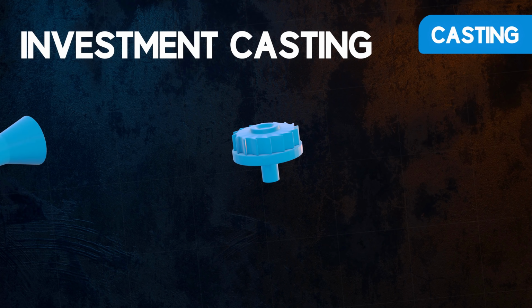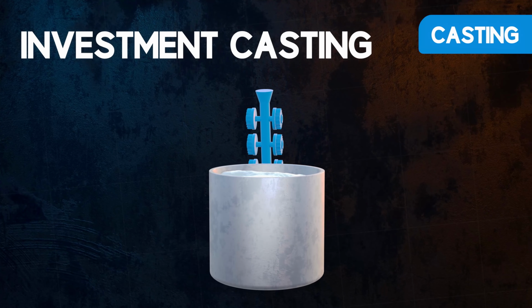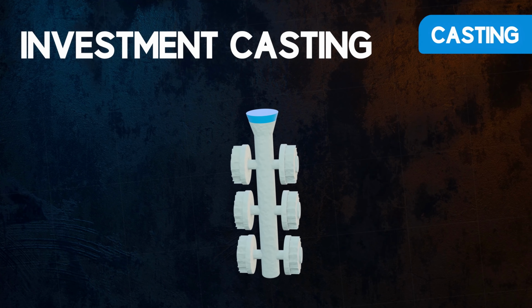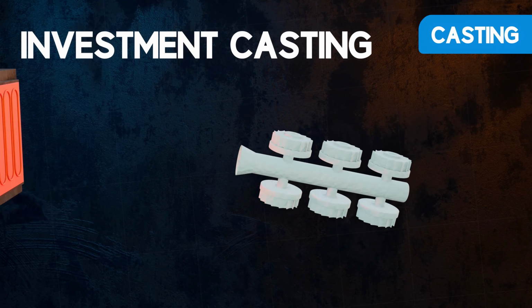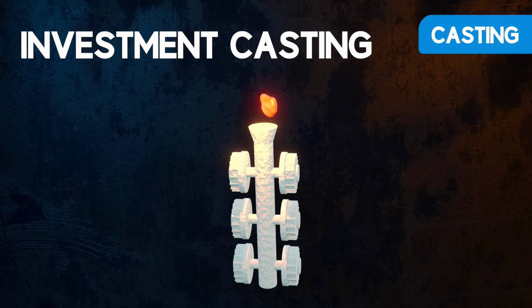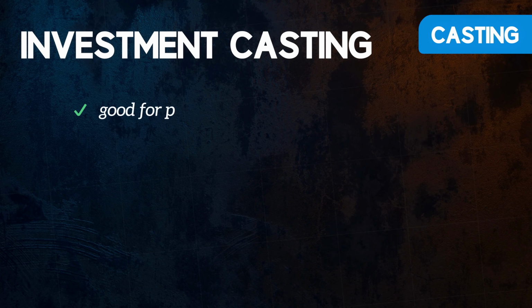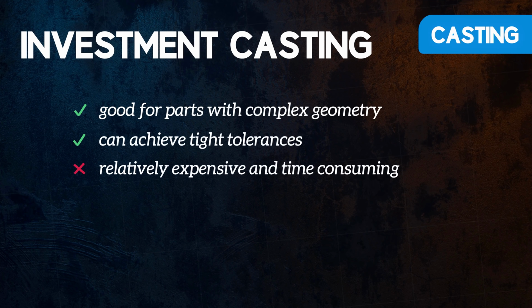Several wax patterns of the same object are created and attached to a sprue. The wax tree is dipped into a slurry to create a ceramic mold. Heat is applied to melt out the wax. Molten metal is then poured into the ceramic mold. And once the casting has cooled, the mold is broken off. Investment casting is good for parts with complex geometry and can achieve tight tolerances, but it is an expensive and time-consuming process.